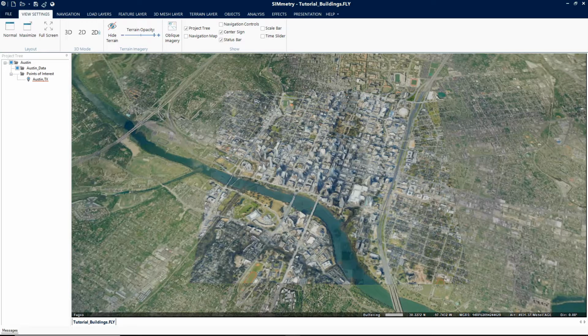This tutorial on buildings will provide you with the necessary steps to create buildings in your project. The building feature allows you to add 3D models to the project by manually defining geometry of the building rooftop and stretching it above the basic terrain, or by loading the rooftop geometry from external feature layers.